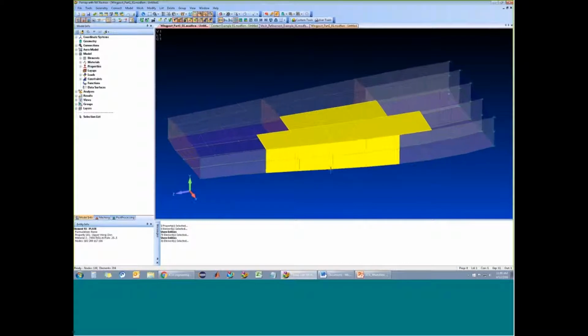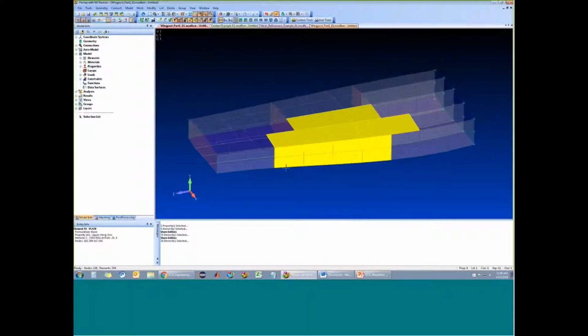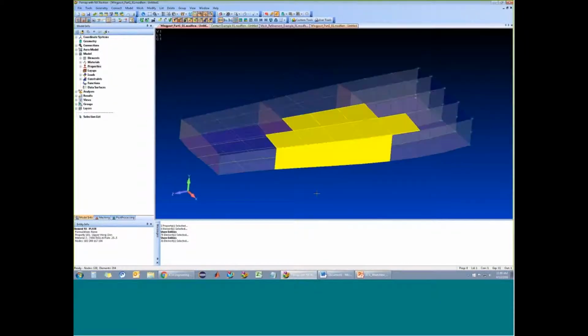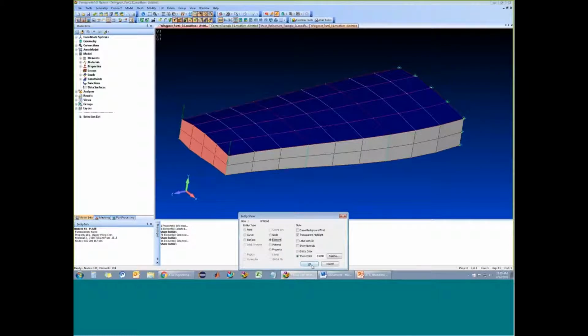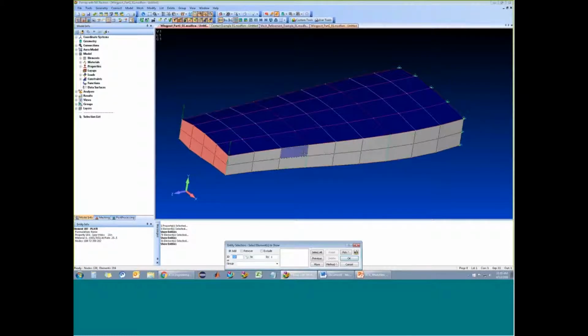And so to speed things up a lot, the Femap developers made this just look at the pixels. So if you're zoomed really far out and your element is smaller than a pixel, you may have some problems. But generally for models, this can be very useful. This also works if you're just doing single select. So as I'm rolling over now, you see I'm always grabbing that front element. It's being highlighted. That can be very useful.